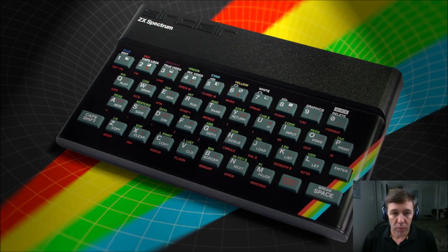In today's workshop we are going to continue our experiments with FPGA using the RTZ7 board developed and manufactured by a company called Digilent. In one of our recent workshops, workshop 4 to be exact, we designed an HDMI test pattern generator, and today we are going to use it as a baseline for a ZX Spectrum video controller.